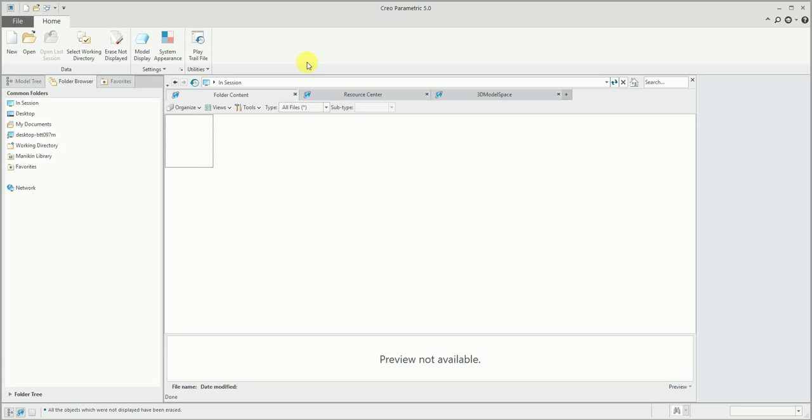After you close machine A and start working in machine B, and you have a part of the same name, then you will face trouble. You will see the part that you assembled in machine A is now showing in machine B. The reason is quite simple: you closed your assembly but did not erase it from the session. So generally professionals are habitual of using this tool.